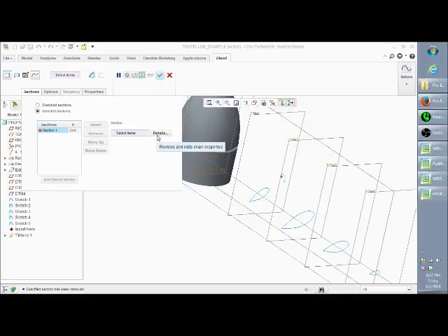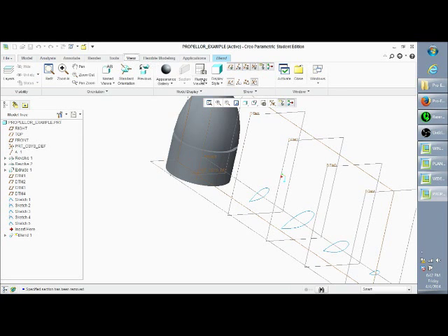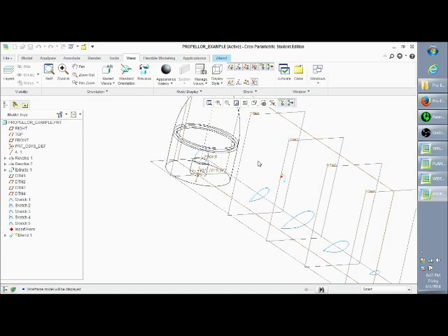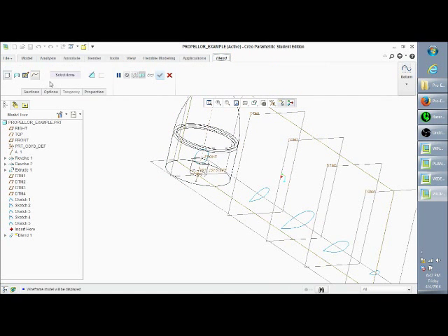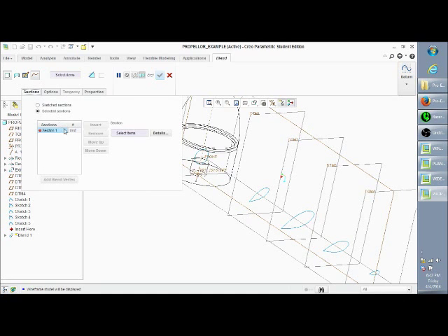So for this one, we want to click in this box right here and find the circle. If it's hard to find, you can go to the View tab, go to Display Styles, then Wireframe. Then your circle will probably be easier to find. And if you choose this method, I'll go back and show you how to find it. So for this selection, you want to click this circle first. Then click the Insert button.